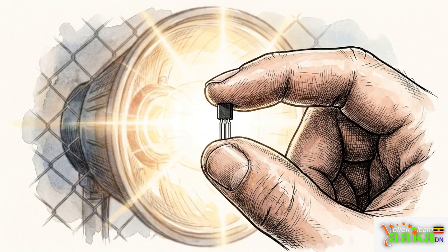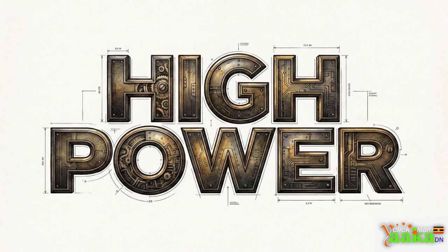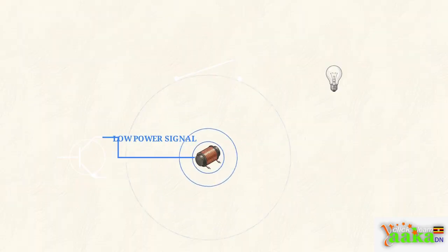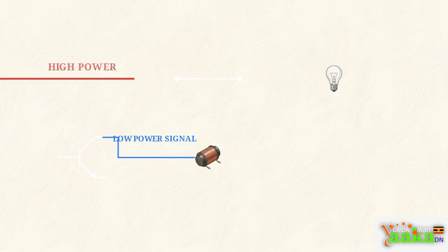However, the transistor is a small part. It isn't strong enough to handle the heavy power needed for a bright outdoor security bulb. Our brain needs some muscle to finish the job. We add a relay. Think of it like a village chief giving an order to a construction crew. The transistor's small signal activates the relay, magnetically snapping closed a thicker wire carrying high-voltage power to the bulb.